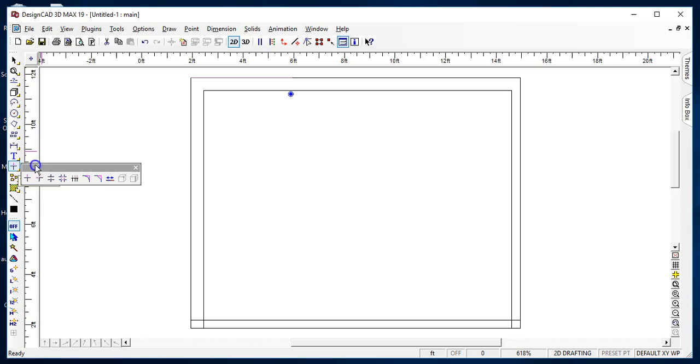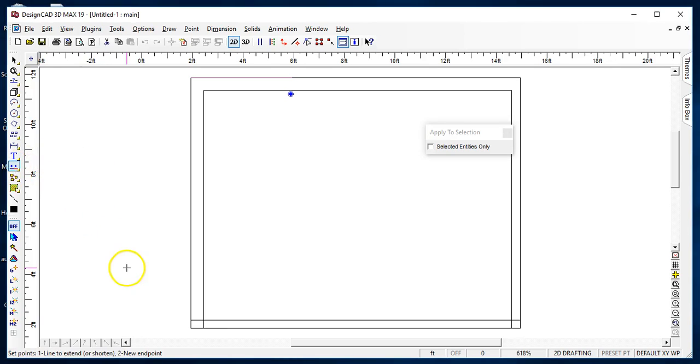This tool here is, I think it's the 7th one in. 1, 2, 3, 4, 5, 6, 8th one in. And this double arrow is an extend tool. I'm just going to double click on that so it stays up. And I can right click now on the end of this, and I can now right click on this point here because I'm telling the tool I want to shorten the line by this amount. Again, I'll right click this and I'll exaggerate. See how I can click this that much shorter, or I can right click and that much, but I want to right click and then I want to right click on this point.